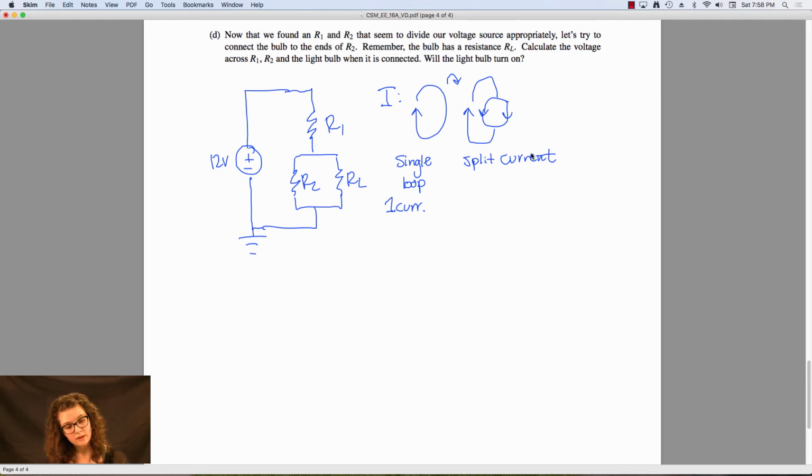We could do nodal analysis on this new circuit once again in order to find what the new voltage will be at this node. We're going to be measuring this. What I'm going to do instead is use series and parallel equivalences along with our pre-derived voltage divider equation to calculate the new Vout.